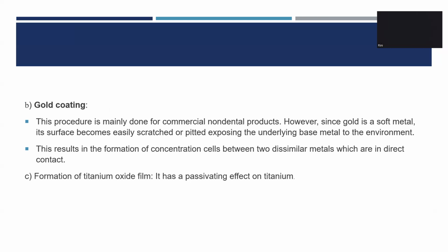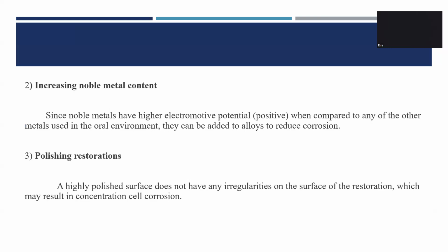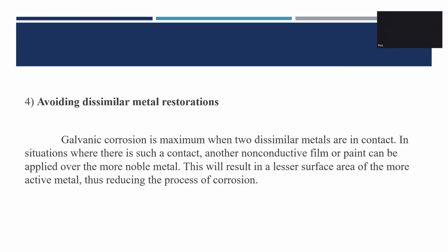Formation of titanium oxide film has a passivating effect upon titanium. Increasing noble metal content. Since noble metals have a higher electromotive potential, that is positive when compared to any other metal used in the oral environment, they can be added to alloys to reduce corrosion. Polishing restoration. A highly polished surface does not have any irregularities, which may result in concentration cell corrosion.